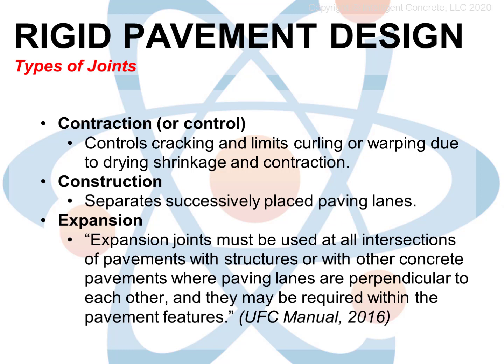Manhole covers, for example, will have a semi-flexible ring of material around the steel collar to provide a little bit of give between the concrete and steel, or there would be a much greater chance of pavement failure at that point. The same is true where one pavement intersects with another pavement or a building. We have to build in a little band of flexibility or something is going to break.